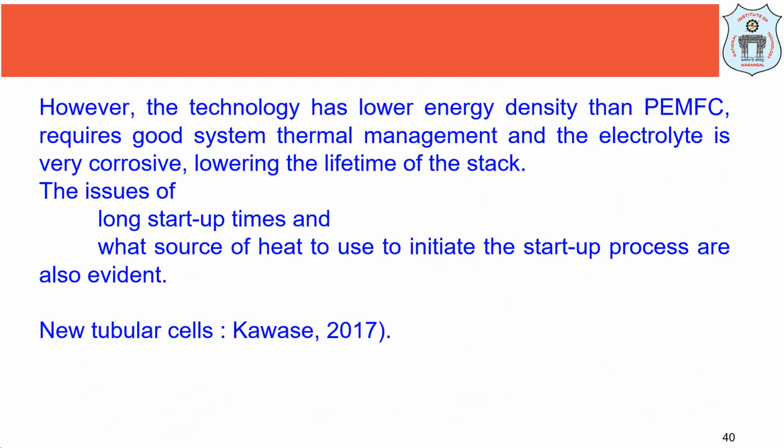Also, it has an issue of long startup time. What does long startup time mean? Instantaneously it won't start working, right? The carbonate has to be formed, it has to reach the surface, right? Then only is the carbonate acting as your electrolyte. So that way there is an issue with long startup times. From shutdown to going to steady state, it takes a lot longer time. That's what long startup time means.